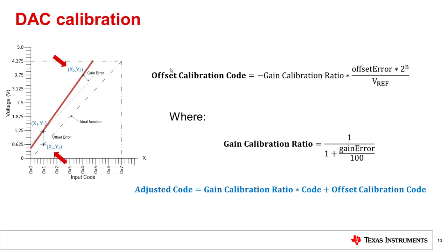You can also program this routine into your digital controller, which can often drastically decrease your system total unadjusted error, but remember that using this method could address a code that is out of range of your controller, so please make sure your programming scheme takes this into account. Next, let's look at an example where gain error and offset error are calibrated.